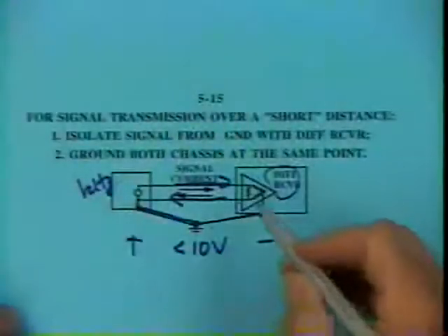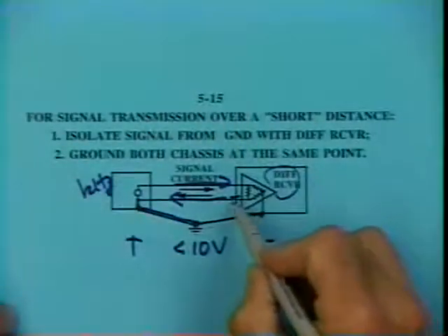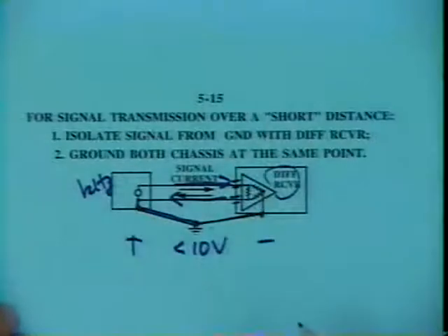Well, if this circuit is near the external wall of a building, we may have a big problem on our hands. But if it's buried down inside of a larger building, even with lightning conditions, running this signal 20 or 30 feet, we might still be all right. Possibly, though, we could put some kind of transient protection on the input to the differential receiver, just in case the voltage briefly exceeds 10 volts.